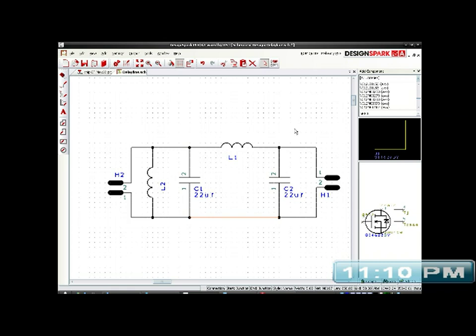We had a massive delay, which was too much of a delay. Just having a couple of jumper leads in series with a capacitor was a massive delay, and I don't want that much of a delay because it was causing huge loads of lag. The delay has to come basically at the end of the pulse cycle.